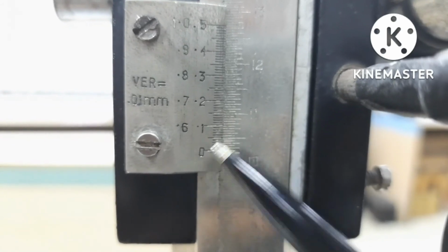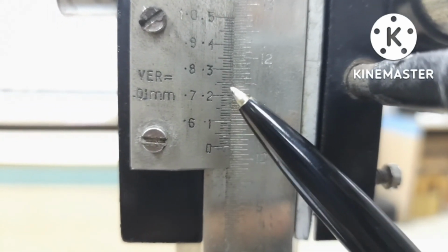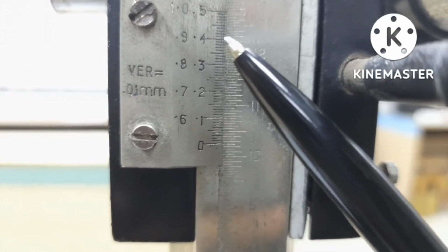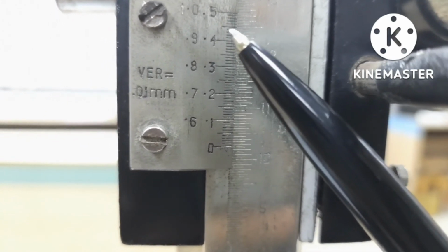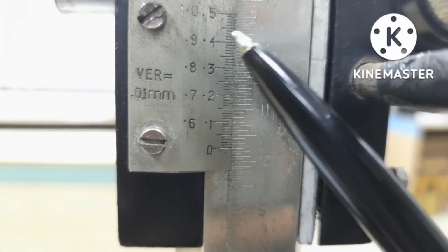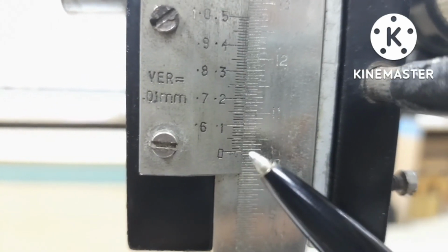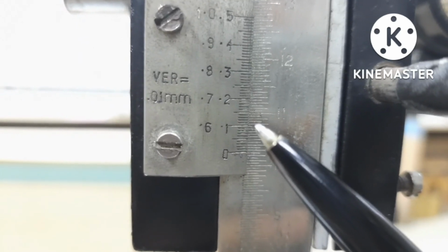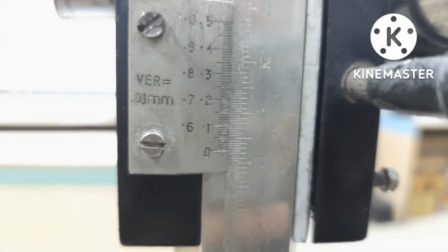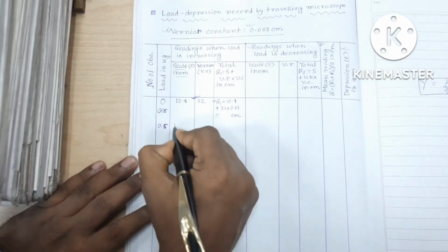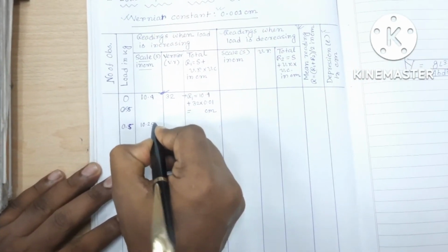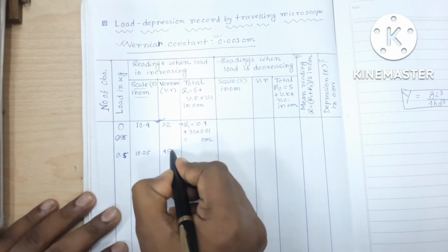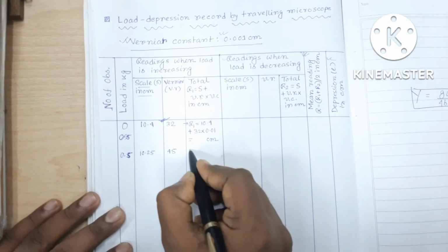I think it is about 20, it is 30 in the upward direction, it is 40, 41, 42, 44, 45. So according to me the vernier reading is 45, and the main scale reading is 10.1, 10.2 and 10.25. Let's take that data. Here it is 10.25 because the smallest division is 0.5, and the vernier reading is 45, and you can get another R1 here.